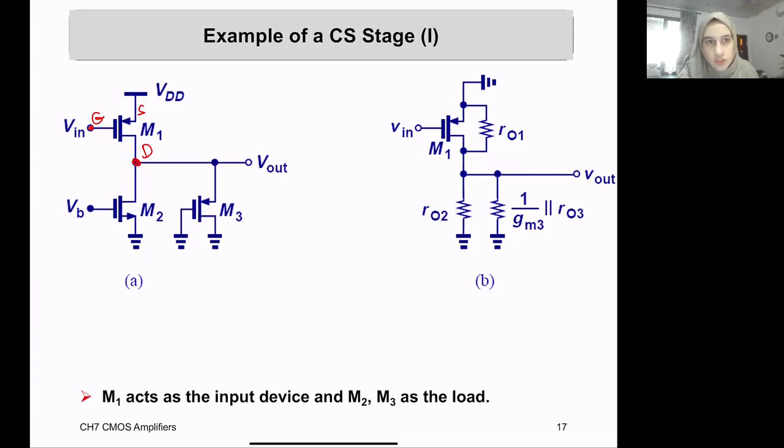There is no degeneration, no resistor up here in the source side. The standard gain of a common source amplifier is minus gm times RD, the output resistance seen at the drain. Now I will identify those components here. So Av is equal to...